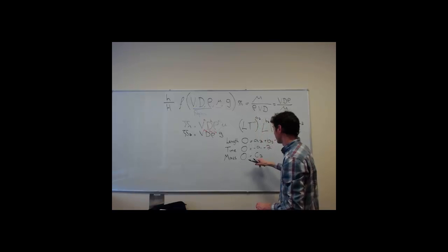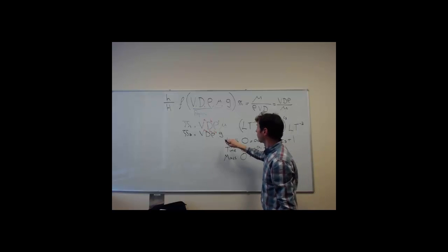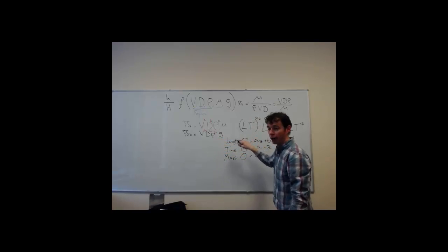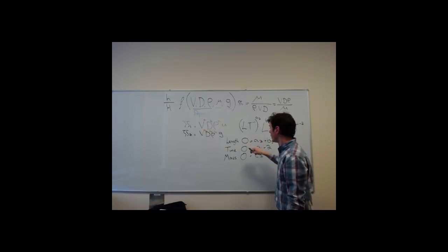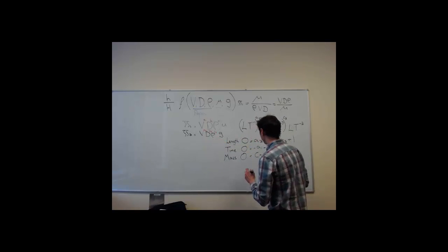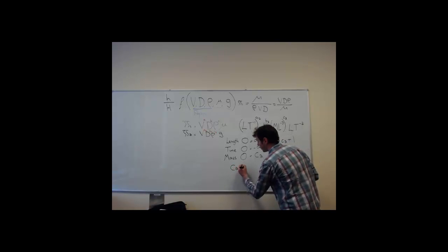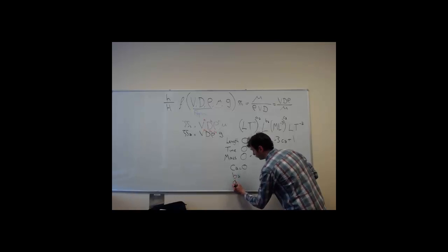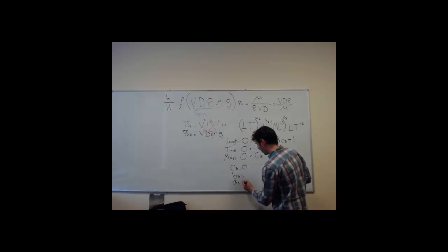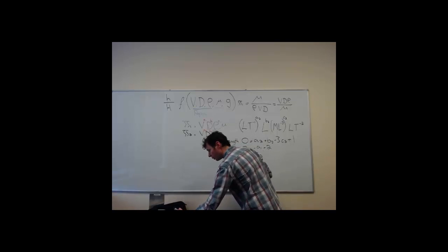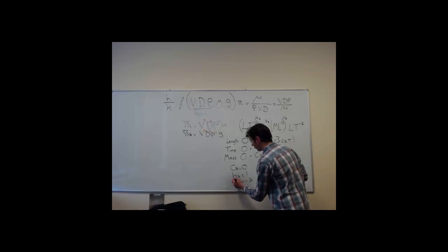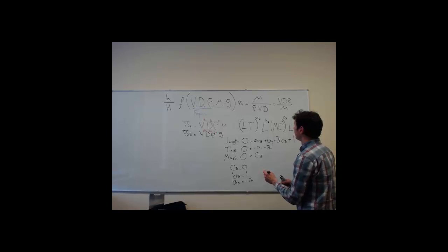So the mass term's disappeared. So C2 is obviously equal to 0. That means that the one term with any mass in it, density, has disappeared from our fundamental group. Which again, we've done this correctly, so there's no problem with that. But as I said before, sometimes the repeating variables do disappear, and that's the case this time. So C2 equals 0, so that's gone. And then A2 is minus 2, and B2 equals 1. Okay, so we can put that back into the equation.